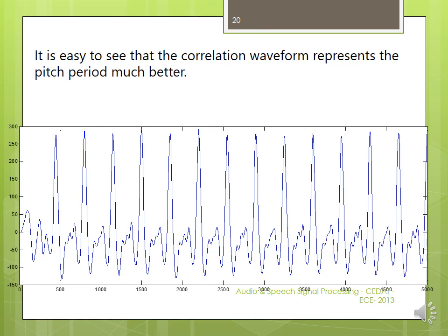You get something like this, which looks much more beautiful than the original sample. What happens with a cross correlation is that everywhere you find similarity, the resultant cross correlation array gets a peak. That is how we can know whether a small part of an array is contained in a larger array. Where we get a maximum, that is the index in the larger array where we found the smaller array, or something very close to it. So it is now easier to estimate the pitch period from this.